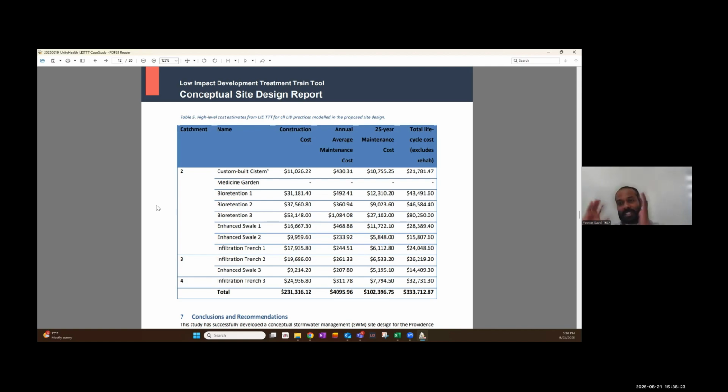But that's the site level. Now, how do we connect this to the watershed scale? At the watershed planning level, what we're doing is those are different models. As an example model, we use the SWAT. They're different resolution. What's SWAT? I know what SWAT means, but a soil and water assessment tool. Okay, so it's one of those models that can be done at a larger scale, at the watershed scale, and we do scenario management for the various watersheds that we have.